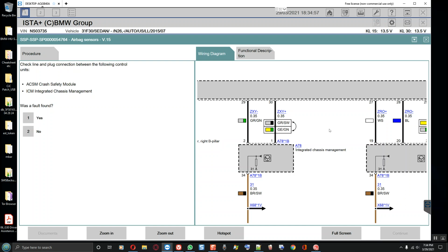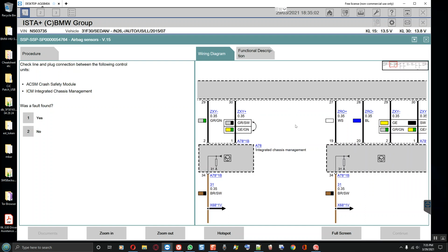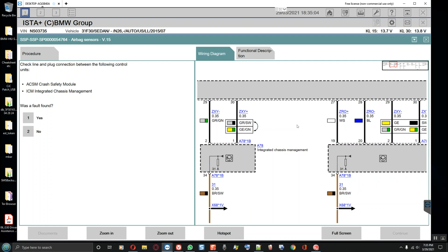Okay. And the fault was not there prior to me messing up the coding. Alright, no problem. Fixing it and getting rid of those other codes for the improper equipment and all that. I believe it's looking for something that's not there due to the coding, if that makes sense. The coding wouldn't mess with it. The airbag module always contains more than one CAFD file.